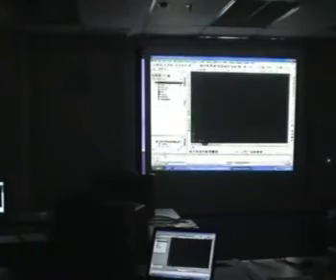Because of this, they looked at Land Desktop, okay, these are the functions we want to retain inside Civil 3D. So you find the functions are the same. Functions are similar, but it's just that the way you use them is quite different. One of the major differences between Land Desktop and Civil 3D is in the platform that they use. Land Desktop uses projects. Like just now I mentioned, you can only open one drawing at one time. If you lose the drawing, it doesn't matter. You can always call the information out again because it's all based on the database.